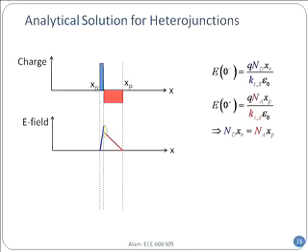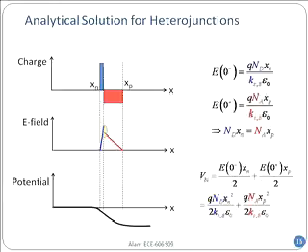Okay, these we have done so many times, we should be experts now. You again realize that NDXN and NAXP, which are the depletion on the two sides, are inversely related to the doping on the two sides. So we know that, right? So you can always write this. And you see this first relationship is essentially a charge conservation relationship. It really doesn't care about whether you have kappa 1 on one side and kappa 2 on the other side. But the second one does.